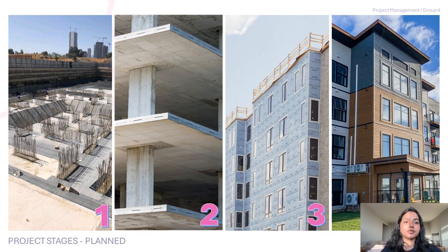Number 1 is achieving the site grade excavation and construction of the substructure. The second stage will be the core of the building, where the columns and slabs will be casted. The third stage will be for walling, windows and doors along with other services. And stage 4 will be for incorporating all final finishes and getting ready for occupancy.